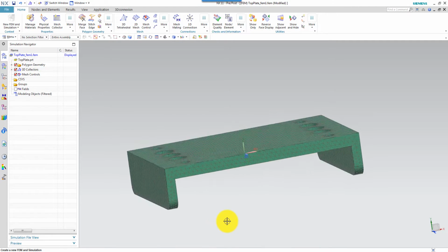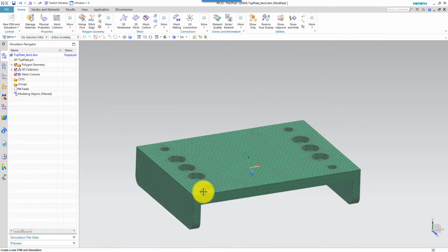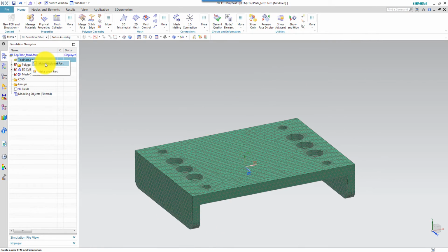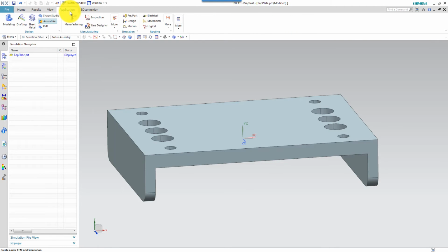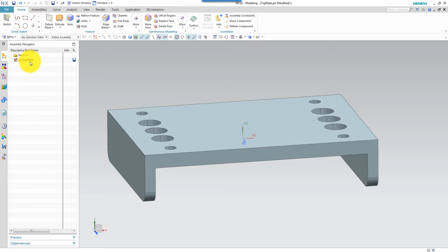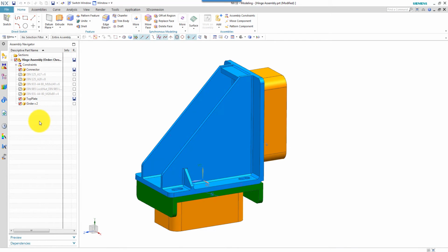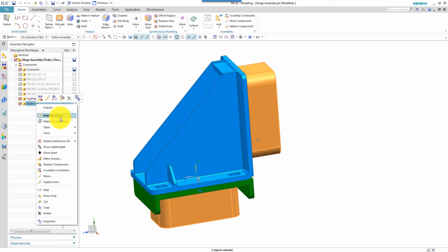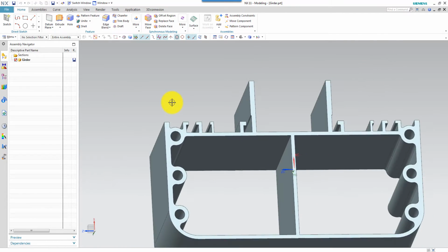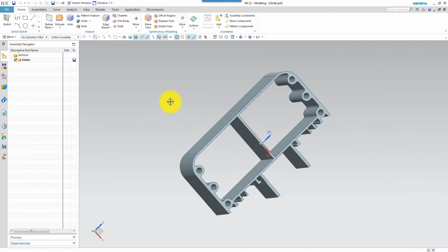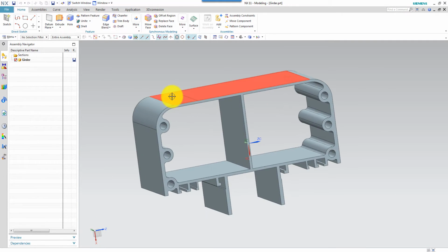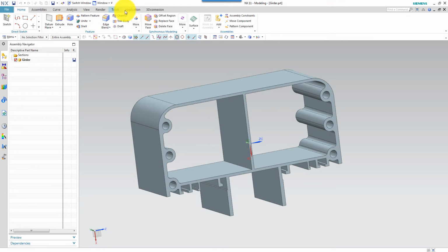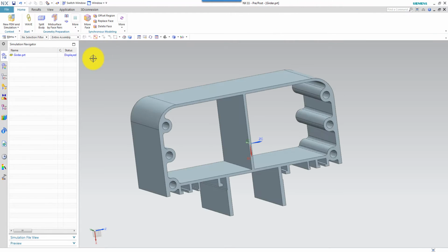There it is. Looks good. Then I go back to the geometry part file, and then I can go to the modeling application, and I go back to the top level, the assembly level, and then I want to mesh the 2 girders, and the 2 girder instances here are represented by just one part. So if I select make display part, I'll get this one on the display, which is copied to 2 instances in the assembly. Then I go to the application again, pre and post.